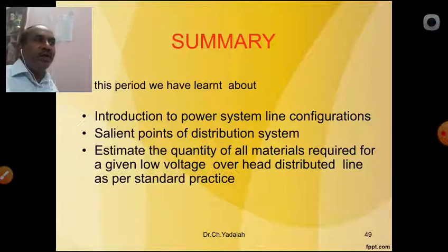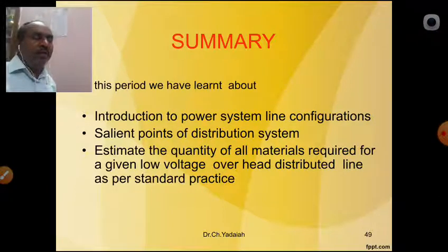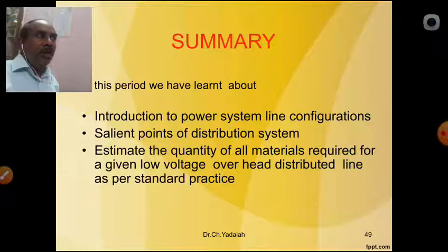And earth sets also, every fifth pole should be earthed. And next, miscellaneous things. So all these are written in a tabular form, then we can say it is a schedule. So these are the methods for preparation of the estimation of an LT line. I think you have some idea of how to estimate the materials for an LT line.